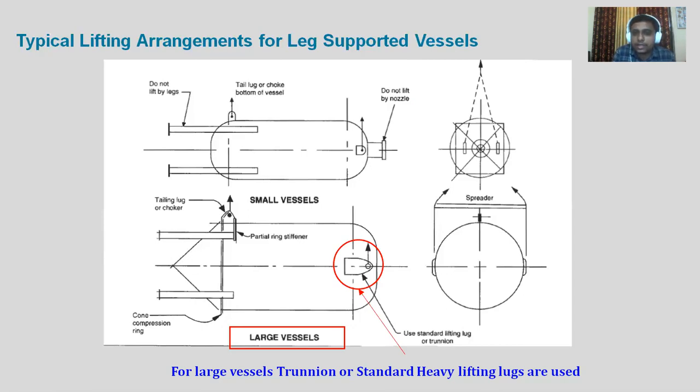When we are looking at that lifting lug, you can see over here, the lifting lug will be having one section modulus, which is called a strong axis section modulus, or the moment of inertia in strong axis. So this entire width of that lifting lug will resist the forces which will be coming. So let's say there will be one vertical force coming like this.